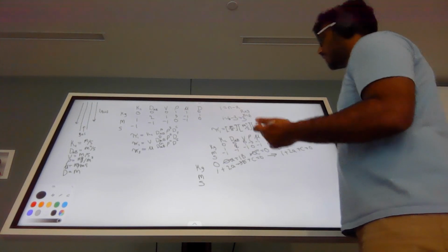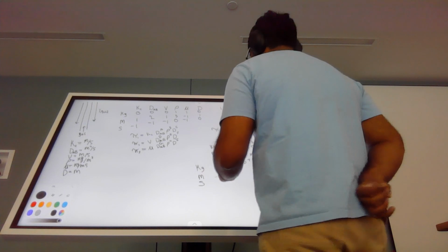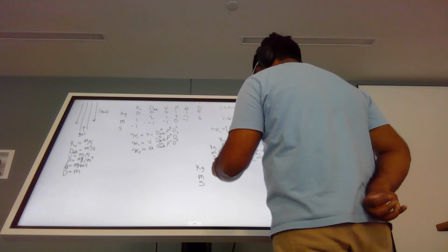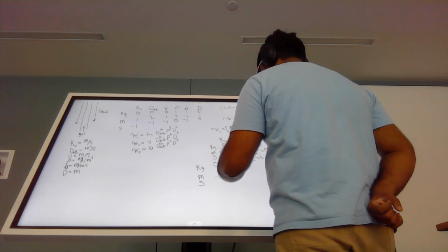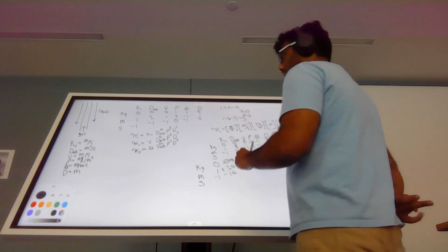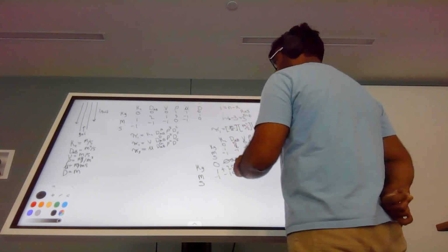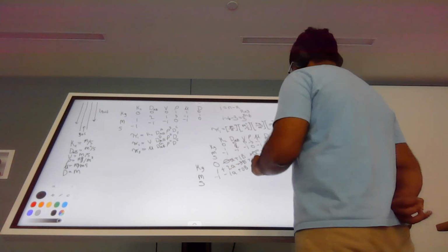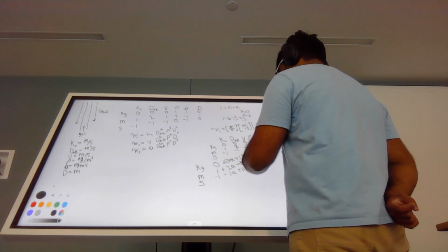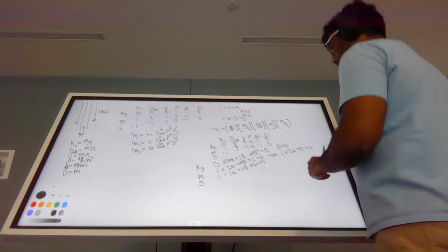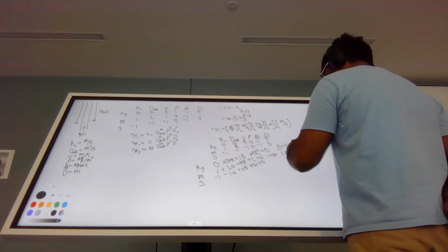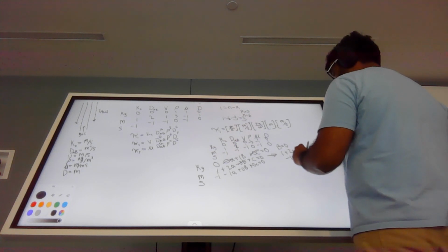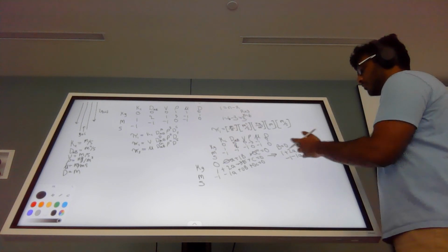Then for the seconds, there is a -1 for the kc, because the seconds is in the denominator. Then -1A for DAB. And then for density, it's 0B. And then for diameter, it's plus 0C equals 0. So we can go ahead and write -1 minus 1A equals 0. And now we can go ahead and solve for A. So A is -1.